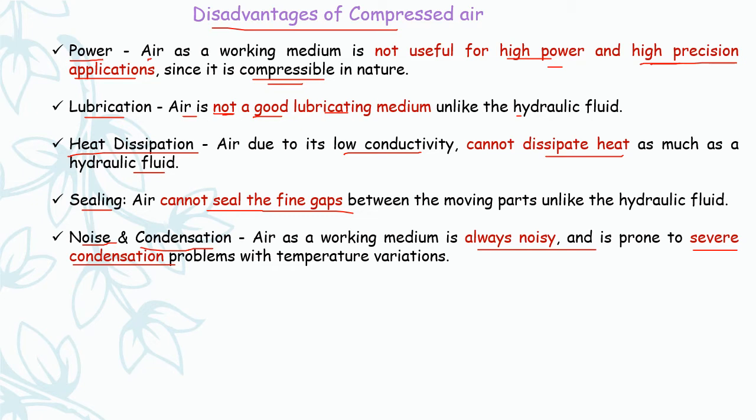And regarding sealing, air cannot seal the fine gaps which are present between the moving parts. There will be small gaps in the moving parts. So if air is used as a working medium, air cannot fill that gap which is present between the moving parts. But if a hydraulic fluid is used, it seals the gap which is present between the moving parts. And lastly, noise and condensation.